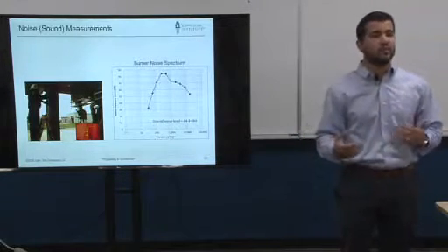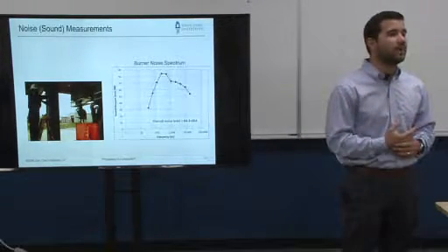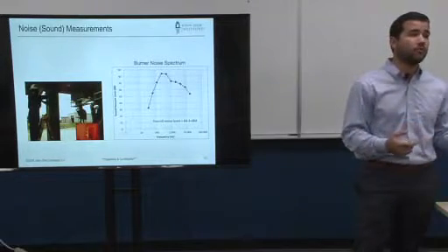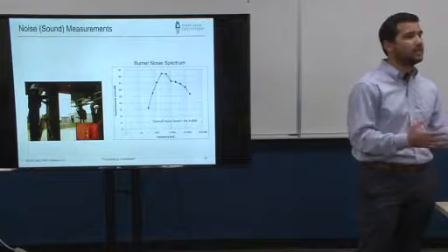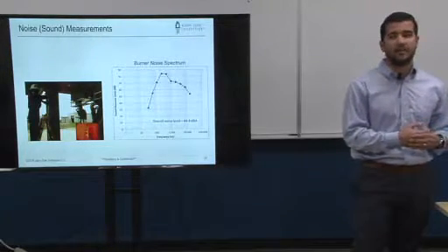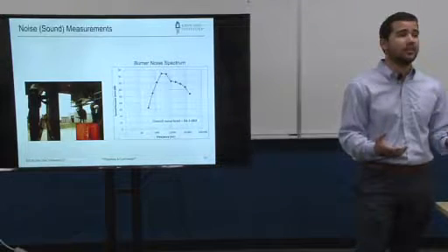Typically in the States, the noise threshold is about 85 dBA. But in Europe, for example, where refineries can be a little closer to the city, you're looking at a noise threshold of like 78 dBA.